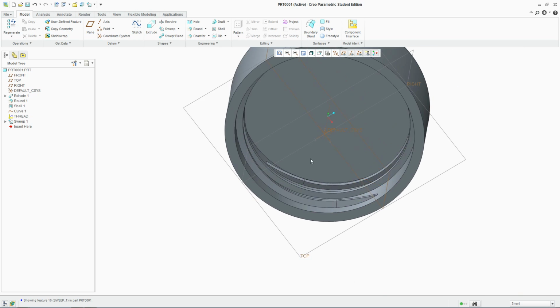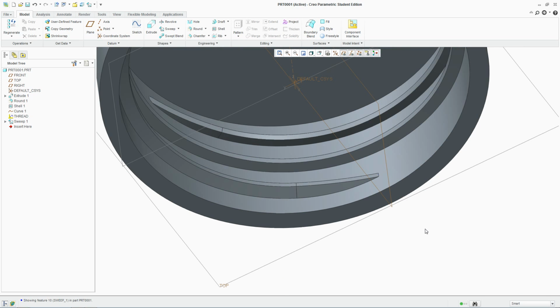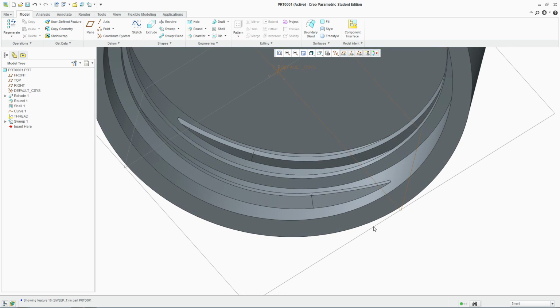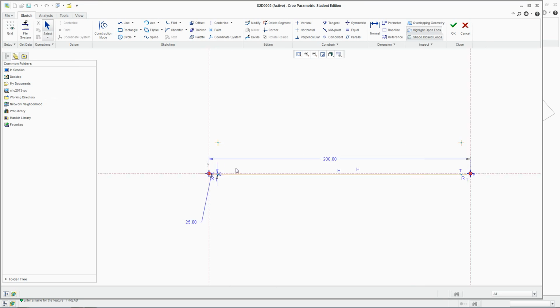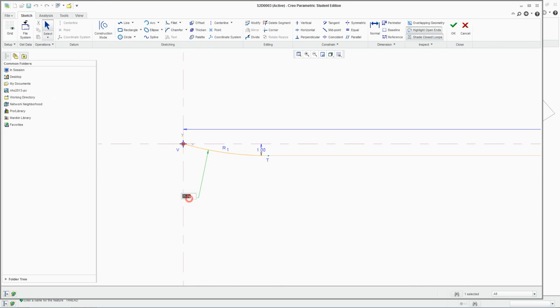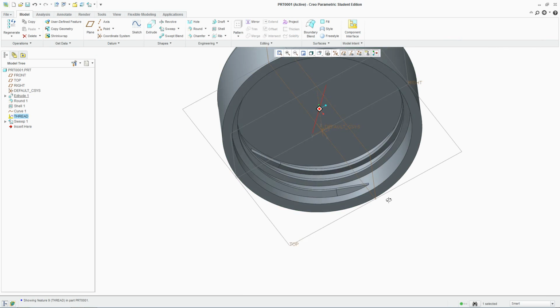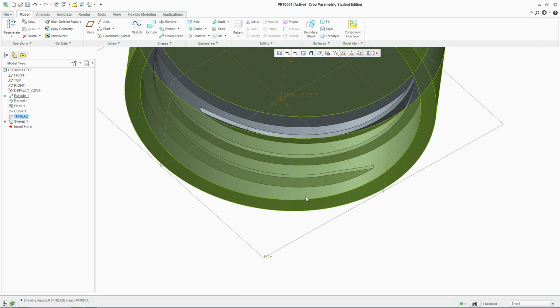So there you go. That's a sweep that's driven by a graph. And if you want to modify this to make that smaller, we can go back to the graph and make that smaller. So we'll make this about 15 so it doesn't become too fast. So now it's a bit less.